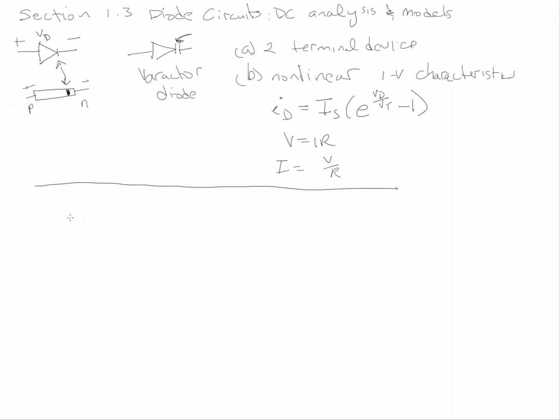And then they give one of the common uses for a diode, which is to make a rectifier circuit. We have some AC voltage source, I'll denote it looking like this, and we'll call this V input. And then we have a diode, and then a resistor. We'll take the output of the circuit across the resistor, so we'll call this V out, plus, minus.